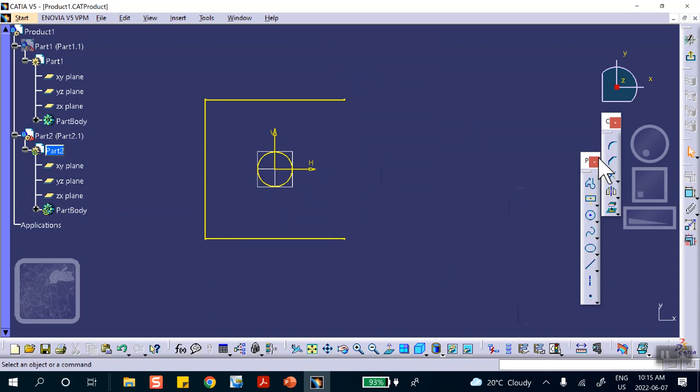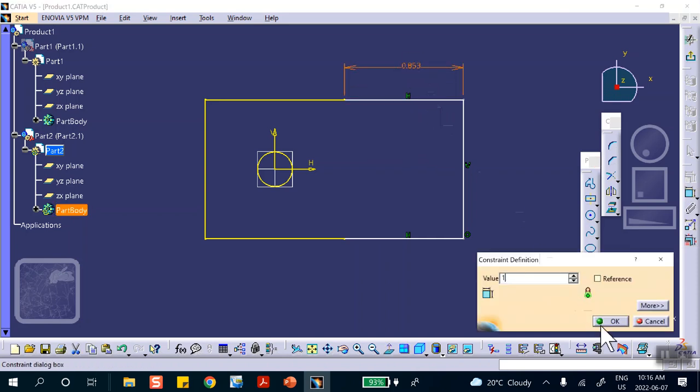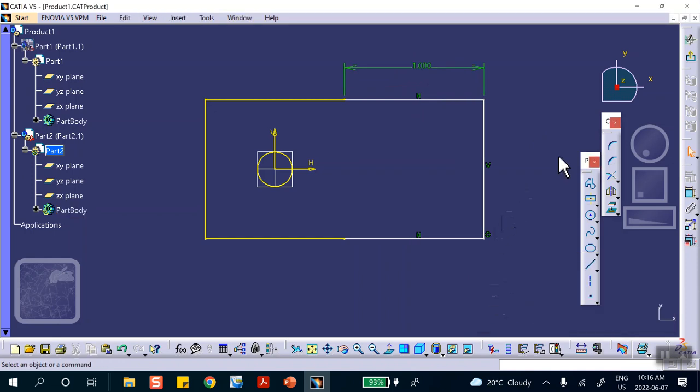Okay, so the rest of the rectangle was like this. It goes from here to here, to here, there. I just have to dimension this thing to be 1 inch because the whole thing was 2 inches. This is already 1 inch, we know that. So dimension this to be 1 inch, and that takes care of it.